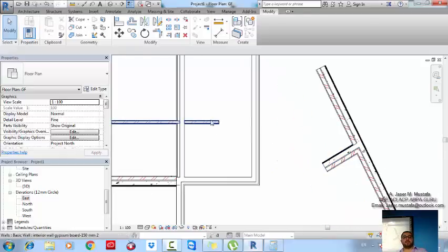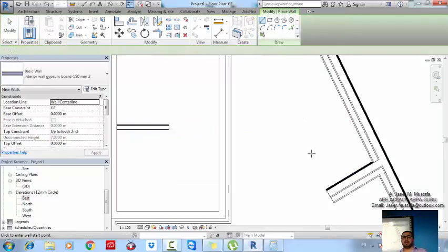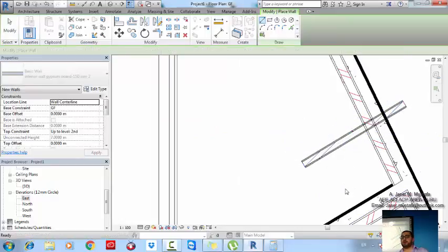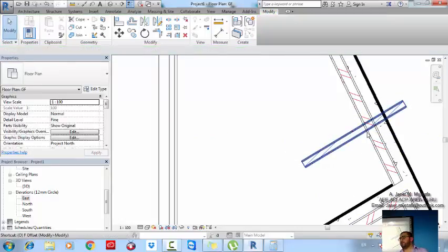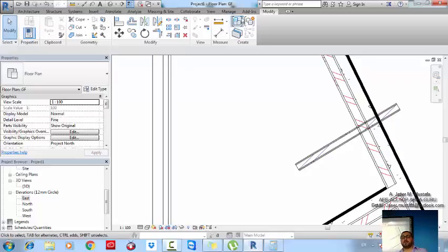materials. If you select this wall, create similar, you intersect with this one, join, it automatically does the join, but if it does not, you can do it manually. Okay? It's only about 2 clicks. In AutoCAD, you need to trim all the lines, then you can chamfer all the lines or fillet it with 0 radius. You have to hatch inside, and so on. Fine? Understand that well, guys? Okay, I want you to do that